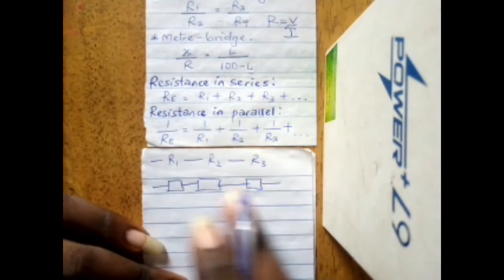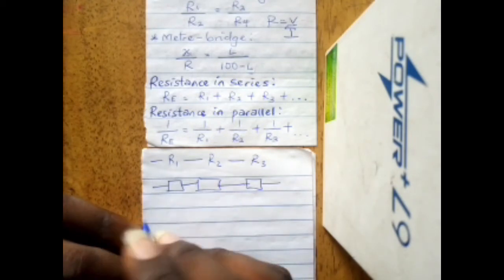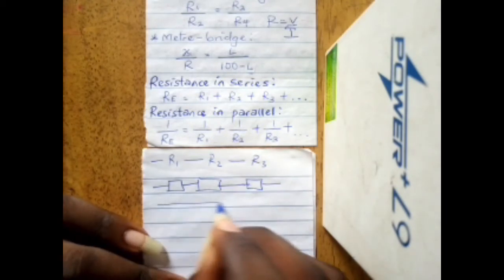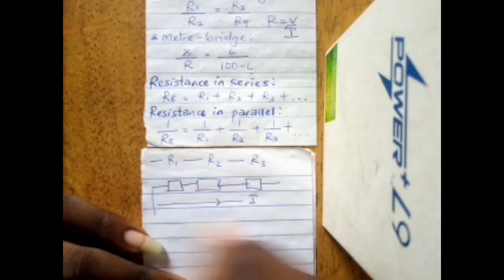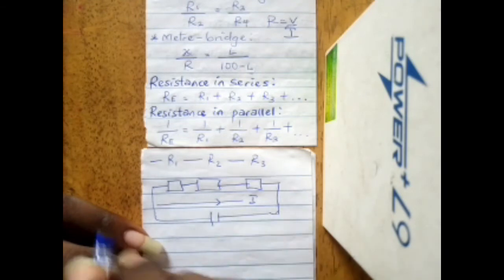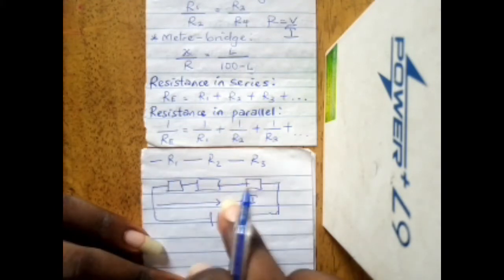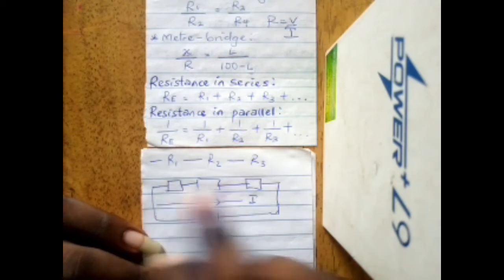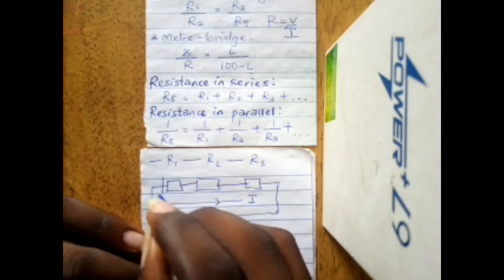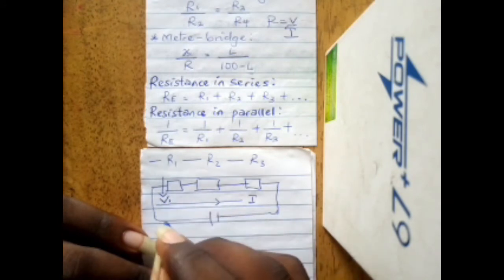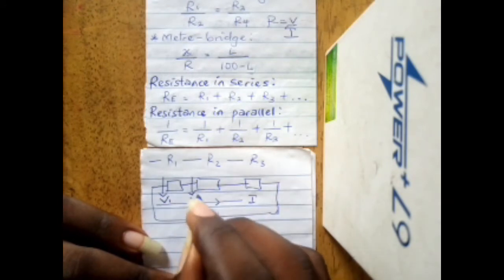In a series connection of resistors, they have the same electric current running through them. They are coming from the same source, the same connection, so the same electric current runs through them because they are connected end to end. But you have different voltage drops, V1, V2.